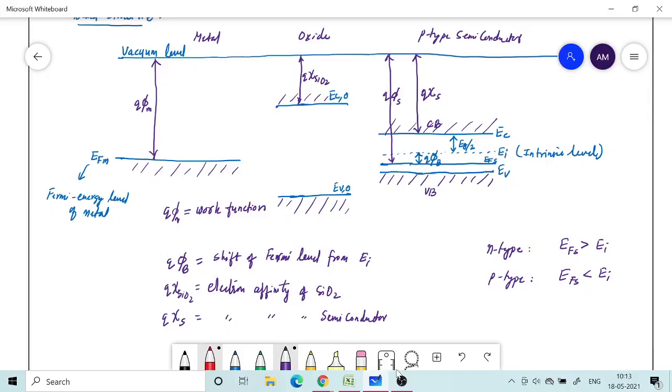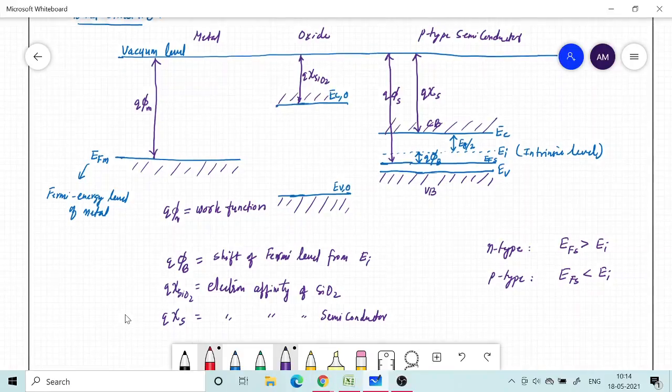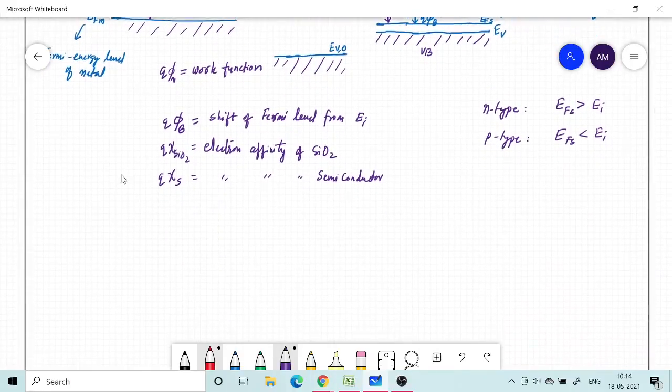And oftentimes we also take a different material for the gate. You can take aluminium, we can take copper. These metals are also commonly employed for gate material. So there is no necessity that phi m is equal to phi s. But if phi m is equal to phi s, then drawing the band diagram is quite easy. You just need to connect all the three. Otherwise there is a lot of physics that will go into it.